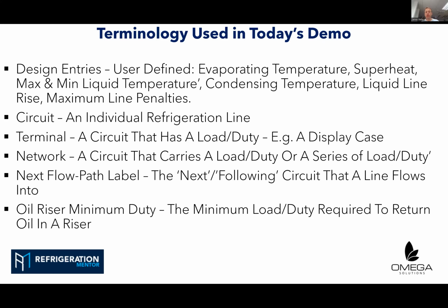Just some terminology, especially for those who haven't participated in any of these demos to date. Just bear with me. I'm just going to try to get there, we go. I can see the full screen now. So, design entries. As I've said, user defined, and it asks for evaporating temperature, superheat, maximum and minimum liquid temperature, condensing temperature, liquid line rise, and maximum line penalties.